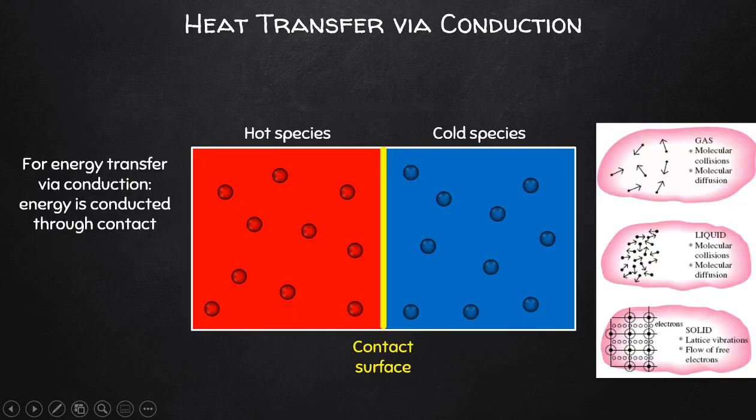Let's consider conduction first. So again, the principle of conduction refers to the energy that's transferred through physical contact between substances. These can be solids, they can also be liquids or gases, okay? And typically then the liquid and the gas would be more or less stationary, right? Remember, particles are always in motion, even in solids, but there isn't a bulk motion in this case when we consider conduction only. Okay, so conduction neglects any motion that would otherwise assist energy transfer.